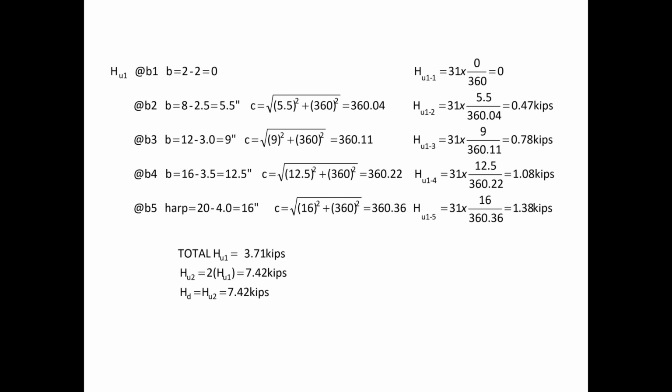One more question did come in. He wrote, does the hold-up force go and stay into the precast concrete element when the strands are released and the element is stripped from the bed? It does, in the sense that the strands are now surrounded by concrete. So it's the concrete that is resisting that vertical force and not the hold down or the hold up in the bed anymore. So yes, that vertical force is still present. It's just being resisted by the concrete in the precast unit.